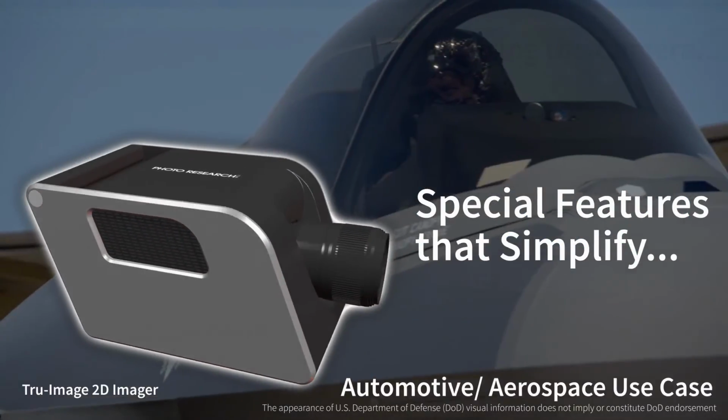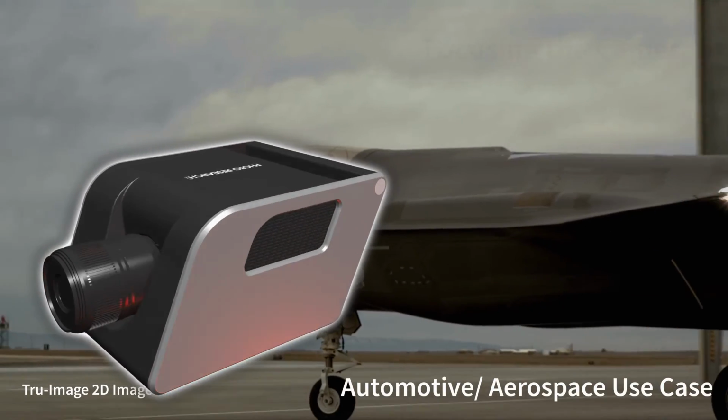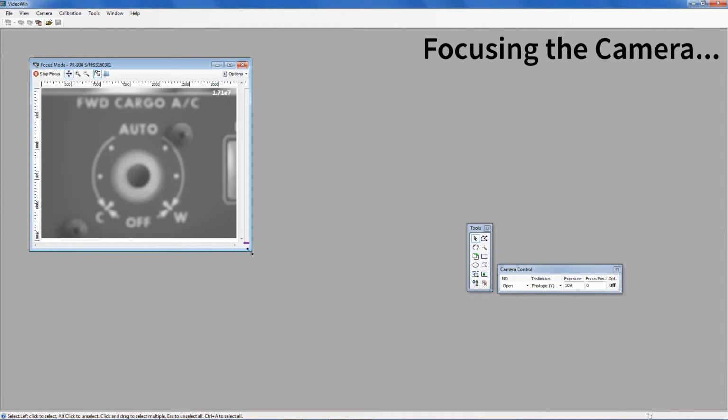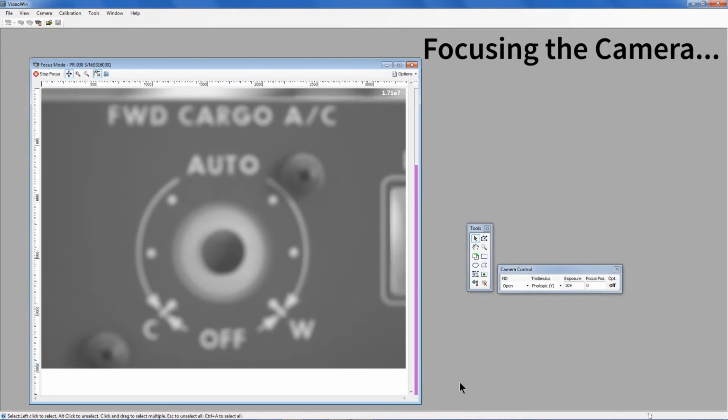Step 1 is to focus the camera on the device under test. Click on Focus Mode in the Camera Toolbar menu. Once the image appears, slowly focus the objective lens until sharp focus is achieved. When the focus looks good, exit out of focus mode by clicking on Stop Focus.